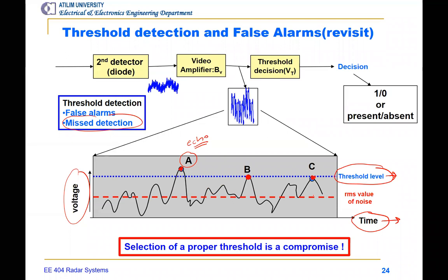So we have to think about how to determine this threshold when we have, let's say, surface or sea clutter, where there is a dynamic environment. The clutter is varying with the time and position of the radar or motion, or the land or sea itself. So we have to make this dynamic or adaptive.